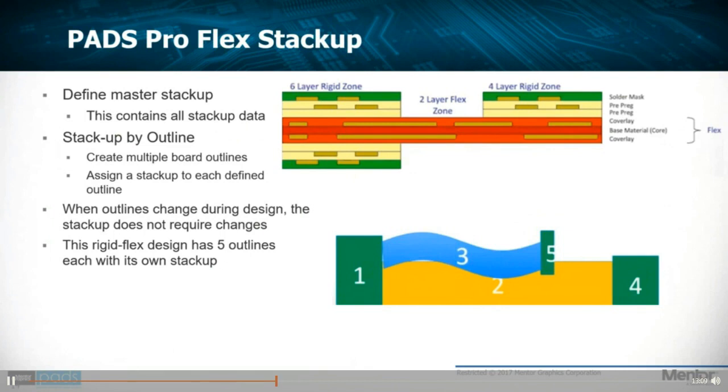Okay. Some advantage of this technique is when the board outlines change during the design process, the Stackup does not need to change. It's carried with that board outline property, and that Stackup definition is going to be propagated through any changes that you create in the outline.